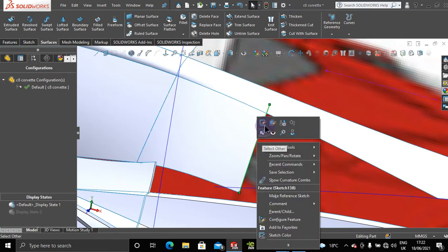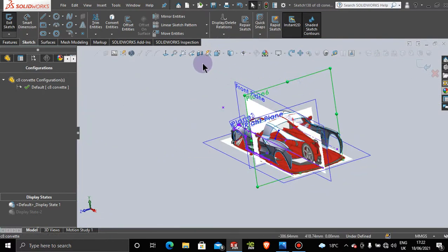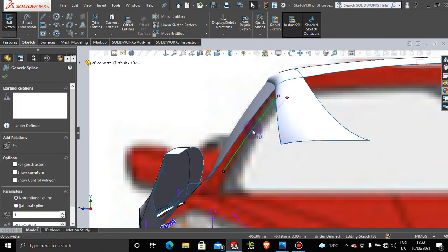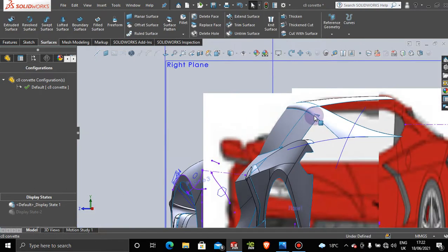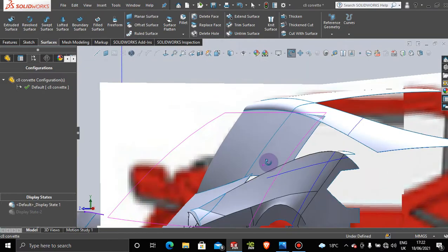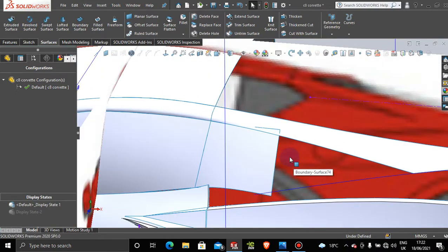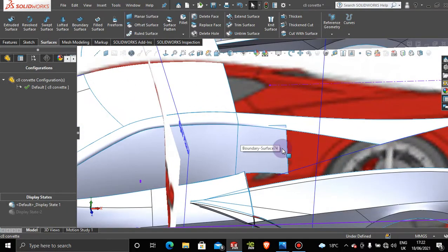So click on the surface, grab that sketch, and then just come back here again, normal to profile, and let's just pull it out a little bit more, somewhere about there. And then exit the sketch. And that's exactly what we wanted. So just a little bit there. That should be perfect for what we aim to accomplish here. Still might be a little bit too much, but we're going to see it when we get to that part.